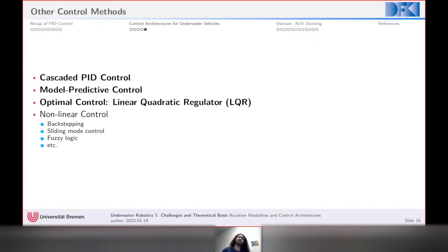This is, of course, where we go into the idea of robust control, and that is something we should do. We are not doing it at the moment, but the way that we are tuning the controllers is what I just mentioned before. We try to identify the system, and based on how much error we get between the measured data and the output of the system, we can evaluate how good this model is.